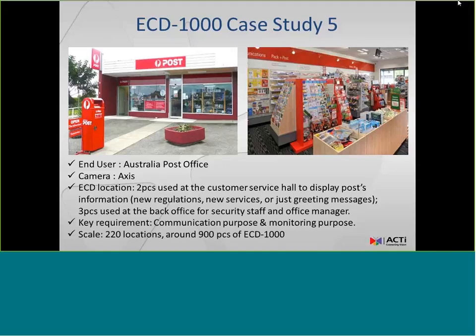Moreover, if I'm connecting remotely, I can use Internet Explorer 11. The maximum resolution of the camera can be up to 10 megapixels. The compression should be MJPEG, MPEG4, and it can be decoded in 4 channels. It will be fine. But if I'm choosing 60 channels on the decoder, it should be in iframe mode. Also, on ECD 1000, any third-party device can be added without any issue if the ONVIF profile is enabled.